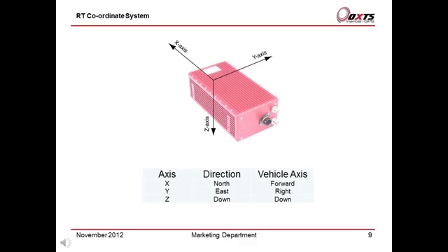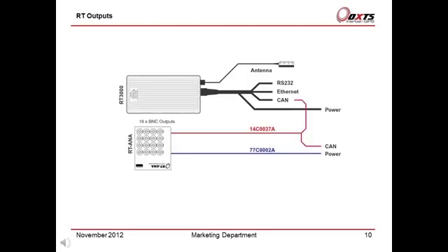Using the RT strut, it is common to mount the RT with the Z-axis pointing forward in the vehicle and the Y-axis pointing left in relation to the car's forward motion. It is important to note the orientation these axes are pointing within the car for use later during the software configuration. Ensure that the correct orientations are applied to the RT outputs in your coordinate systems.